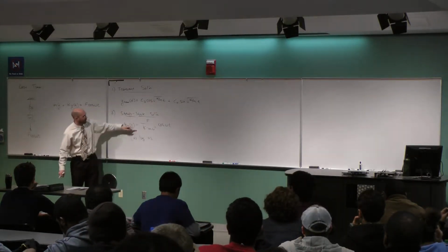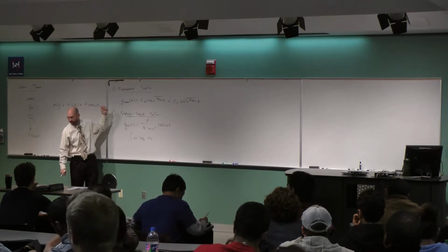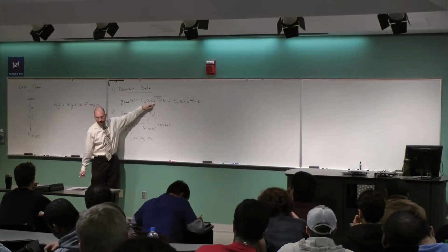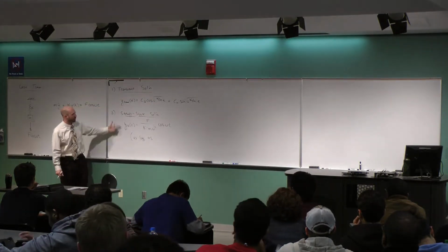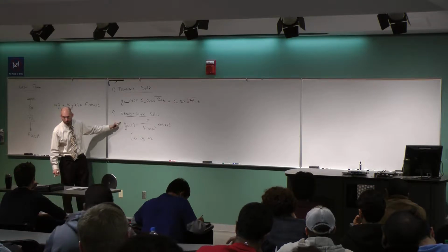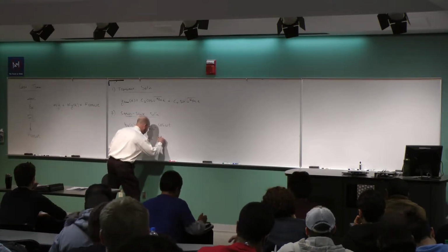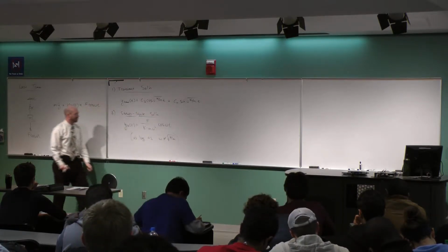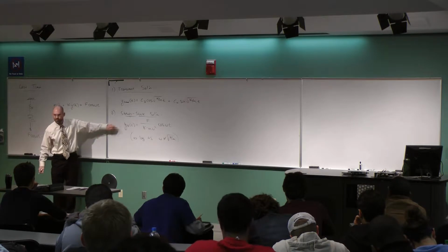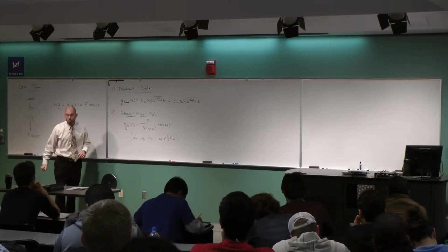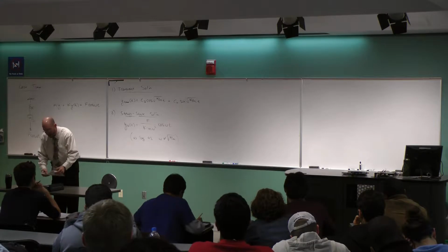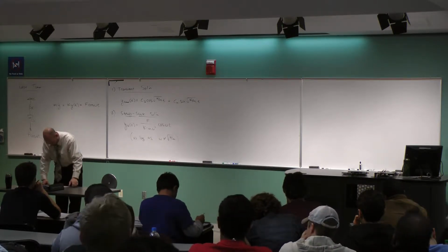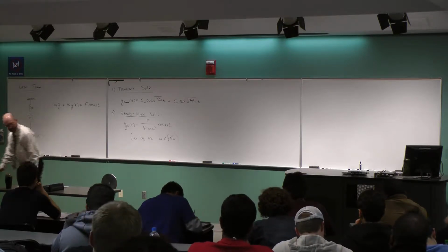As long as I don't force it at exactly the same frequency as the natural frequency, if it vibrates freely on its own, then I don't run into any math problem when I solve for those constants. So this is as long as omega is not exactly equal to root k over m. Every other possible value of omega, this works for the steady state solution. We will take a look at what happens as I approach root k over m when we get the final answer. I think we left off there.